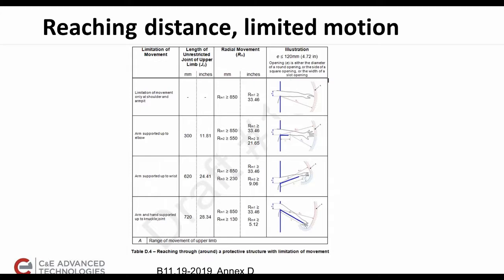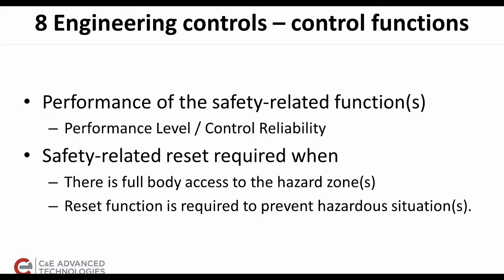There's also data on reaching into openings with physical restraints and so on, again, to give you an idea of how a guarding system can be designed so that you do not have access to the hazard.